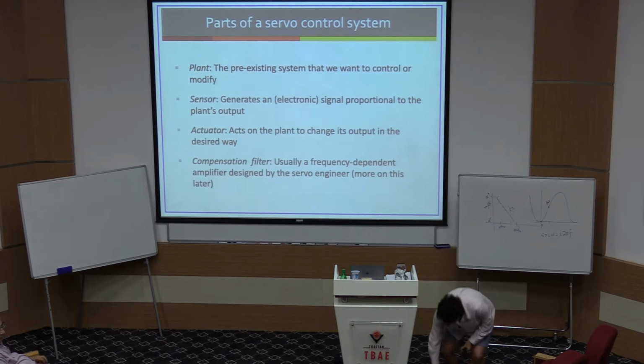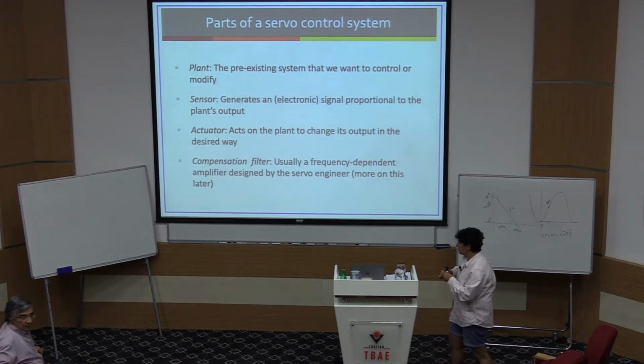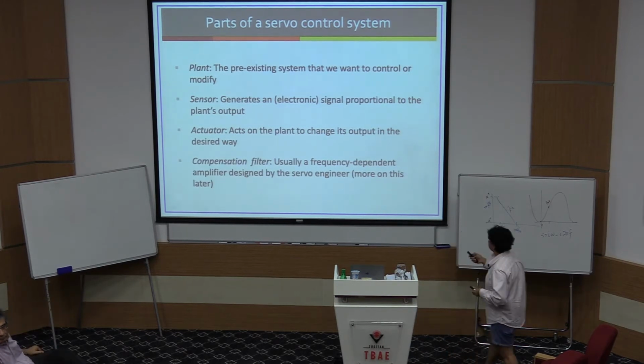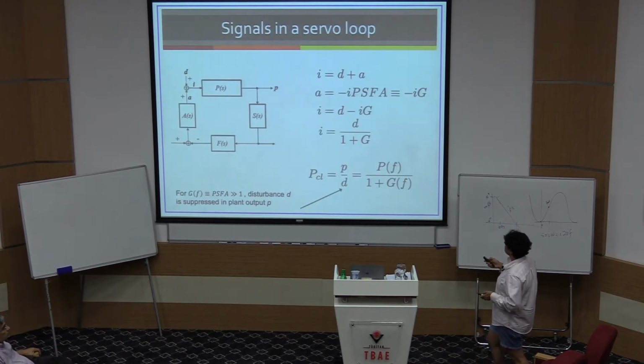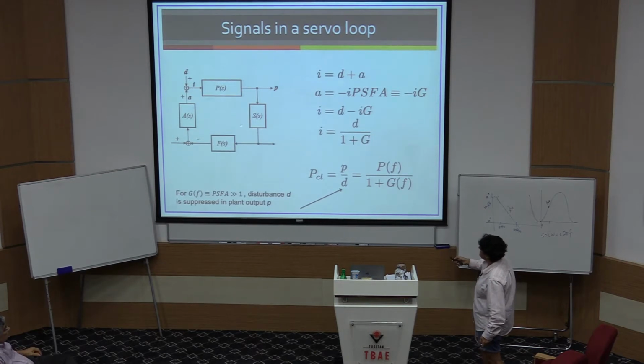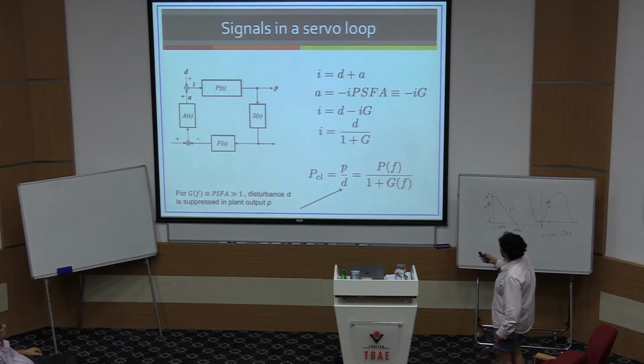And so now the beauty is that as we go around the loop, we can just multiply out P times S times F times A. And so A over here is simply equal to I multiplied through all these objects, okay? That's it. And we define this PSFA as a quantity G, which is itself a function of S. Each of these is a function of S. So now we just plug back for A in this first equation. I is equal to D plus IG.